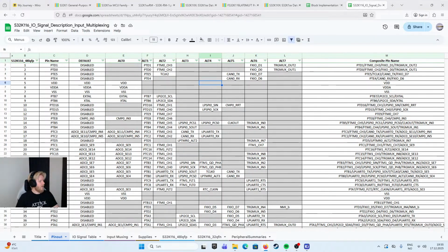With a lot more functionality. And we're only focusing on power ground, crystal, debug interface, a LIN network or LIN controller, and then maybe some IOs for a display, without knowing what I use. Is that a SPI channel maybe, or I2C? I don't know. We'll get to that.